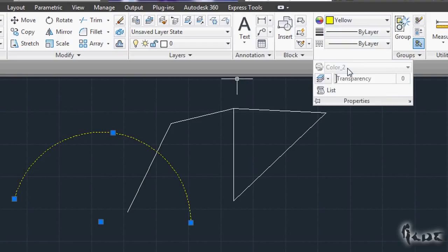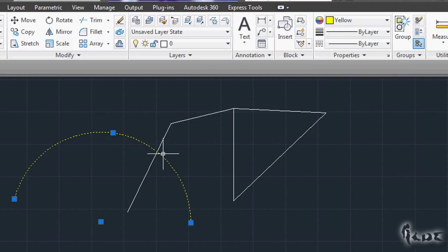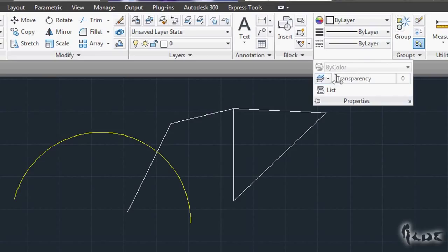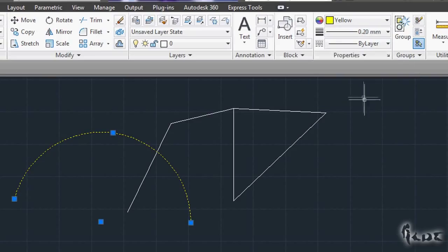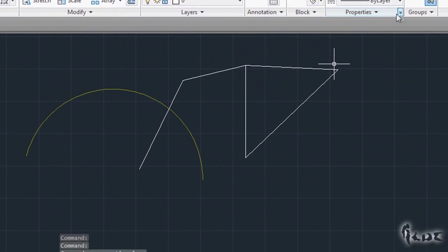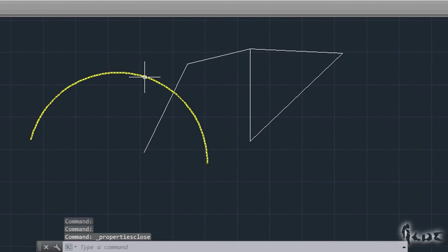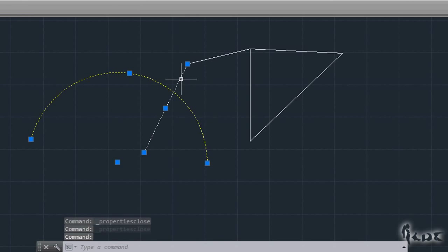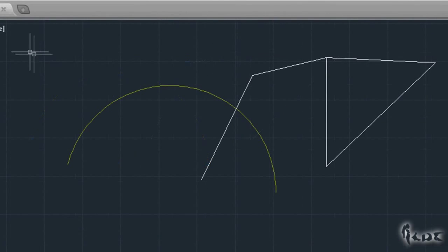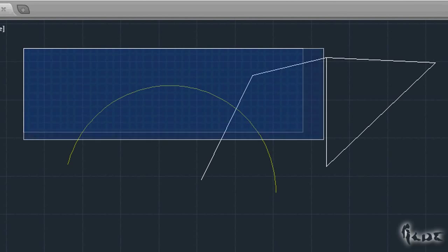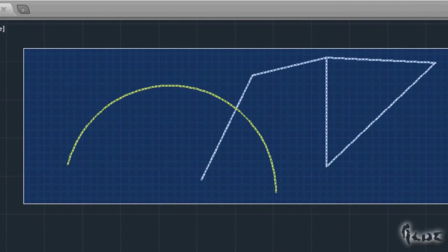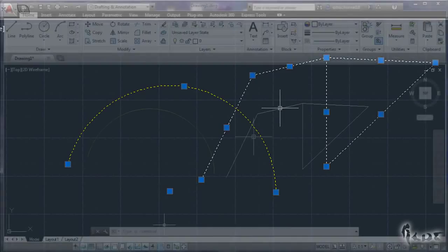For example, select an object and go to the Properties section. Here you can choose color, thickness, kind of line and transparency. Just click at the bottom. These are just related to the object currently selected. You will need to select more objects to apply the same properties all at once. To do this, you can select objects one by one by clicking on them singularly, or you can simply click and drag your mouse across all the objects you need to select in one single shot.